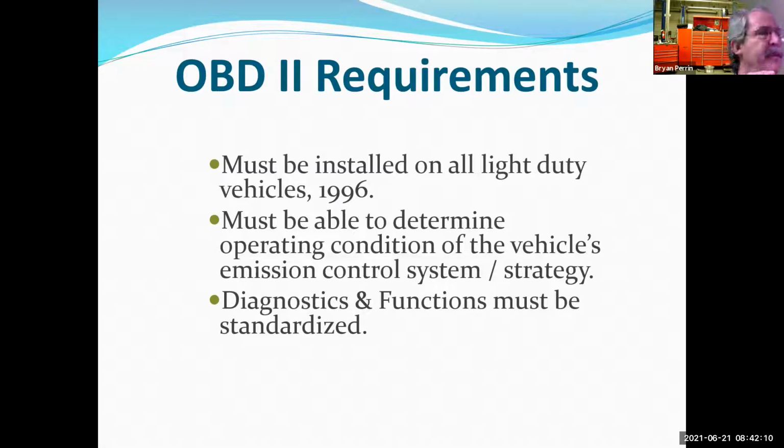So again, we're back to the same but different. Diagnostics are similar, but not the same. Functions are going to be similar, but not necessarily the same. But when it comes to how the modes work, that is standardized. The modes themselves are standardized. The rules that they have to apply to are standardized. When I get out of OBD2 and get into the enhanced side or the manufacturer side of the computer system, all bets are off. They can do a lot of things they're not allowed to do here.